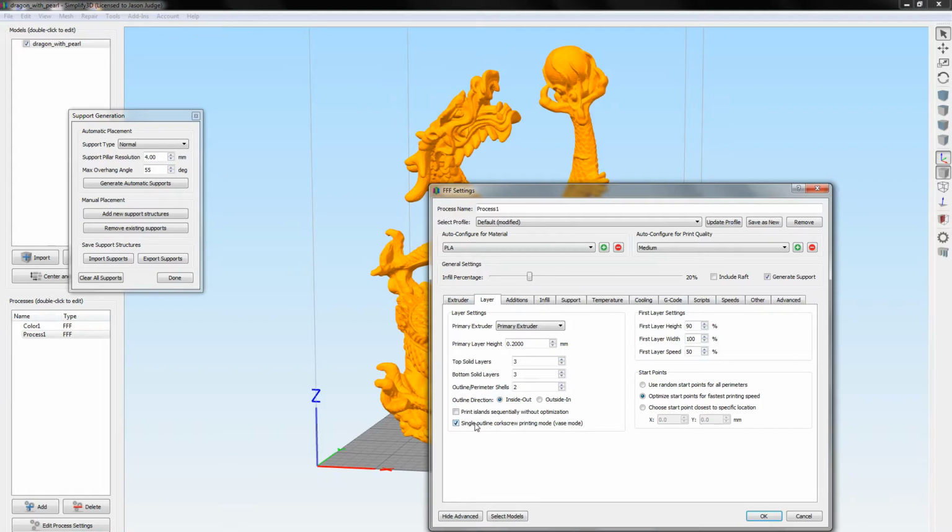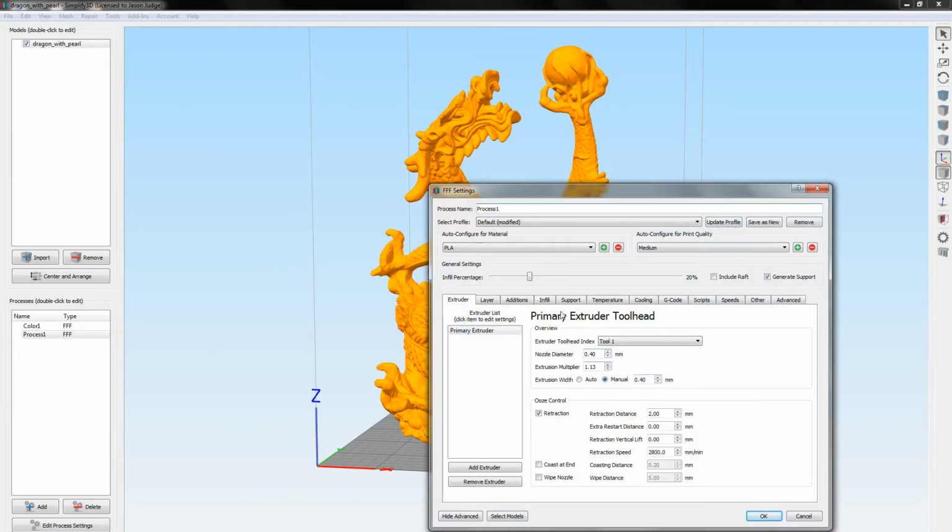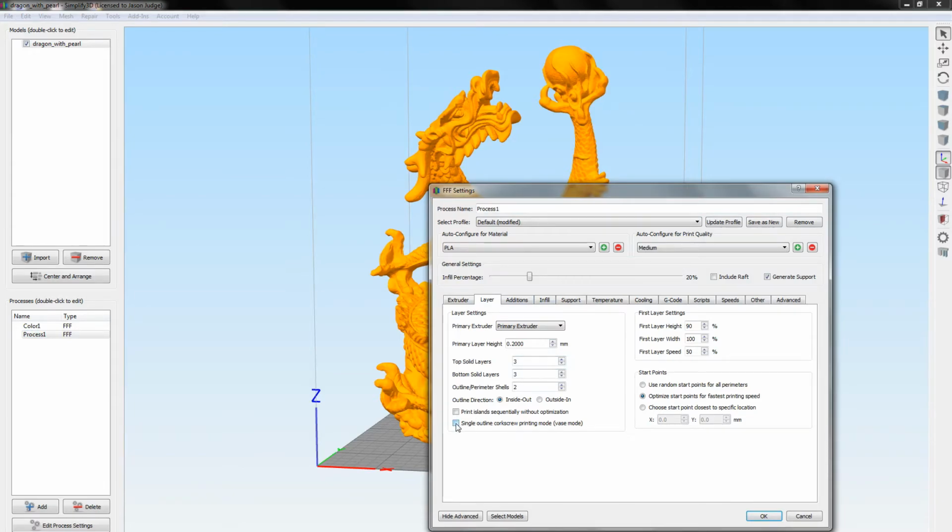One more thing that I want to mention is spiral or vase mode. You're going to hear this a lot in 3D printing, and it's good to know what it is. This setting basically creates a print out of one continuous line of print with no stopping until it's finished. You can have a bottom layer and a top layer if you need to, but the perimeter or wall will just be one line thick. And you won't have any infill or supports when doing these types of prints, but you can have a raft if you need to have a good foundation. It's great for doing really fast prints and using the least amount of filament.